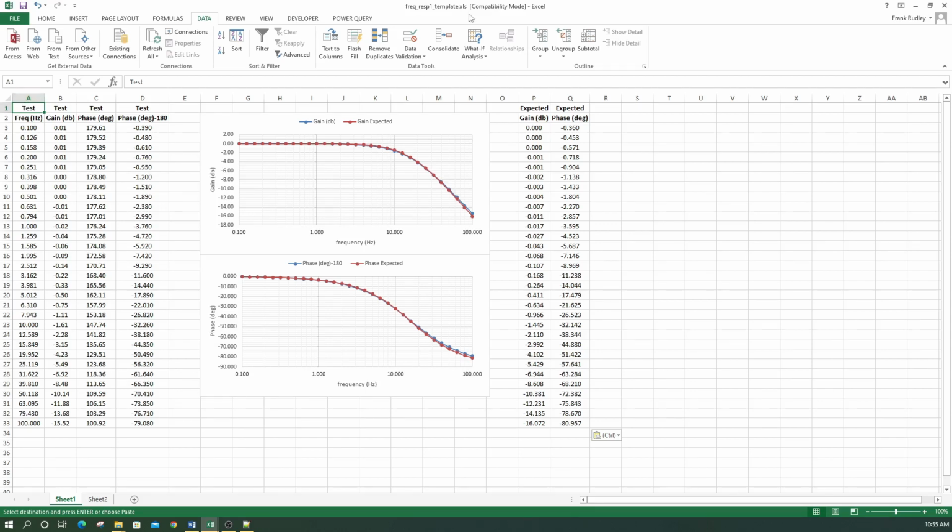So this is the gain, and this is the phase. If we look close to 15.915 hertz, we can see we have close to minus 3 dB and close to minus 45 degrees. So that verifies it. The Solartron is a very good tool for doing frequency responses, especially out in the field, testing actuators, testing electronic circuits. It's very good with digital filters. If you need to verify a digital filter or an analog filter, it's a very good piece of test equipment.